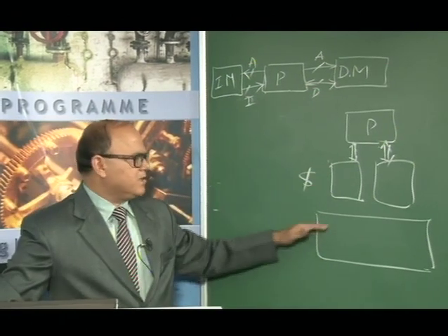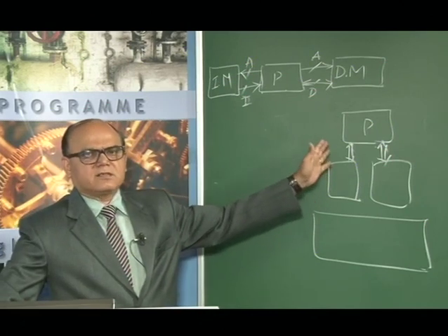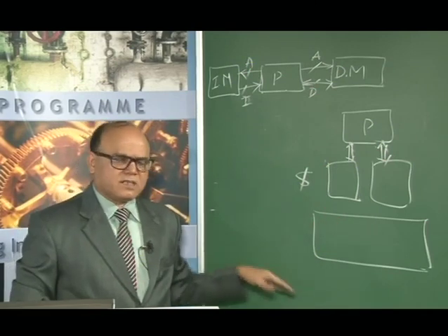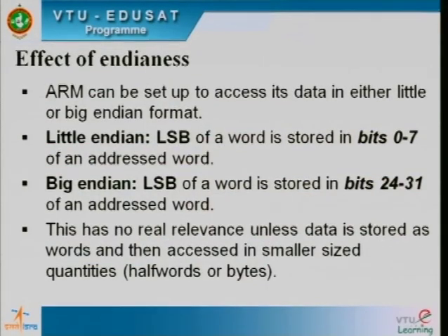The different levels talk about the hierarchy, whereas in each level I have either the memory split vertically or the entire memory split horizontally, right? This is what the memory architecture is, right? The difference we said: von Neumann is simple, but Harvard provides a better access rate, right? That's what we have. Since von Neumann provides a unified memory, naturally the instruction and data should go together, right?